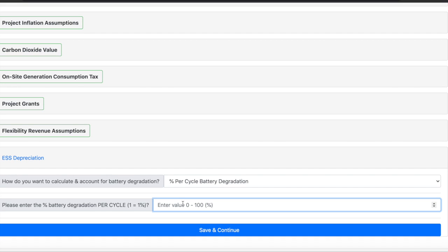We will then degrade again, and through the cash flow you then get a degraded revenue that is related to that degradation of the battery, because obviously as the battery degrades, it's less able to discharge and reduce grid import tariffs. It's less able to discharge energy and export to the grid. It's less able basically to access either cost reductions or revenue streams. So it is really important to think about this.